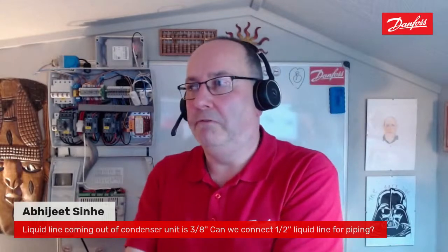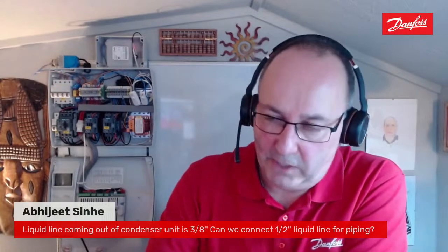It's a bit like, take a solenoid valve, for example. If the connection is 3/8, is 3/8 the correct size, or is 3/8 just the size of your expansion valve? That might be right for the port size of the solenoid valve. That might be right for the duty of the solenoid valve, but your line size might be different. So always check your pipe size based on your velocity that you want in your suction and your liquid pipe. Don't take it as read that because we've got a 3/8 connection on the condensing unit that the liquid line can be 3/8.